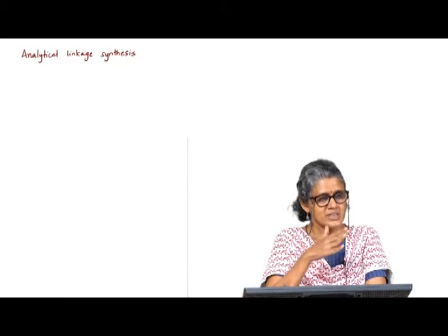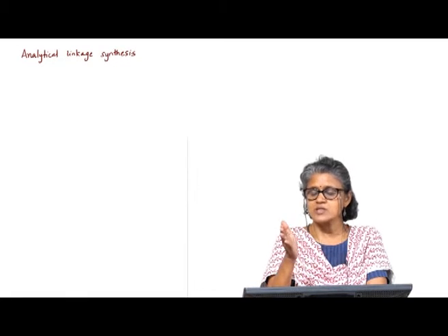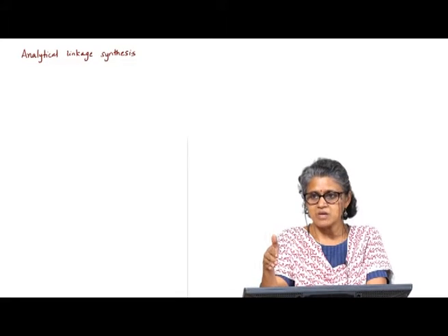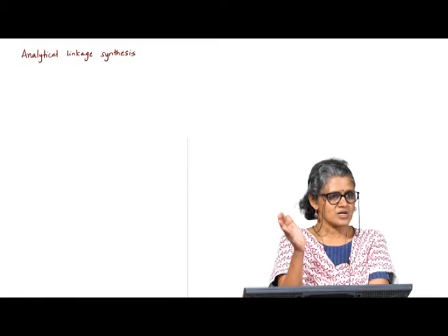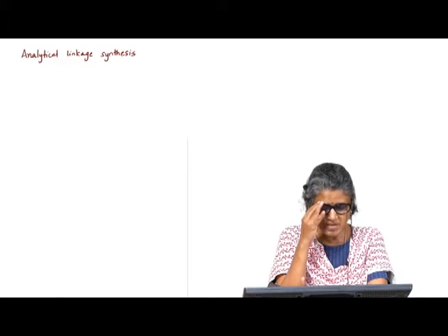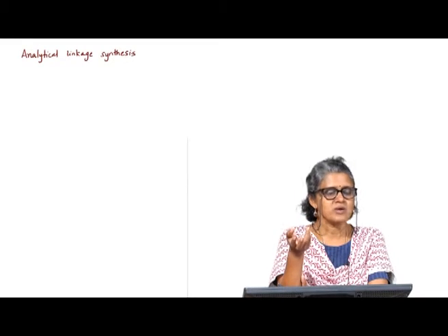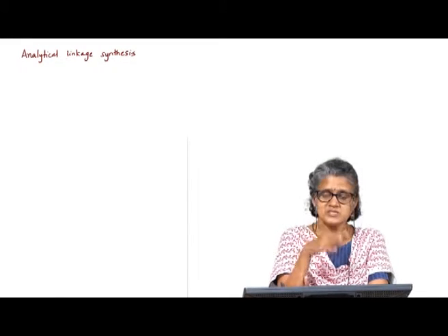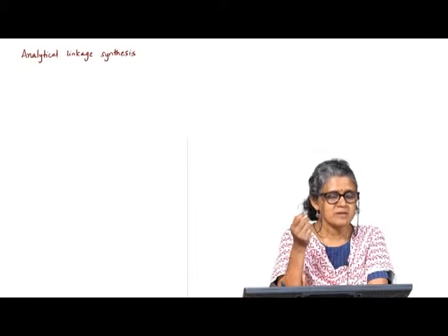Say I want a linkage where, when the input link has a certain angular velocity, I want the output link to have a certain angular velocity. That is not something we were able to do with graphical synthesis. We were able to say, if it attains a certain position, I want the output link to attain a certain other position. So it was based more on displacements, but in many cases you may want a combination of displacement, velocity, acceleration, where you are involving time derivatives.